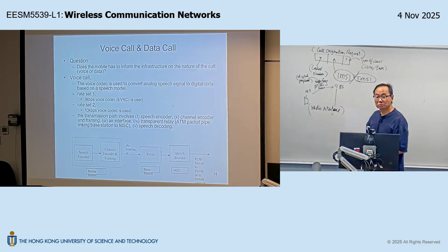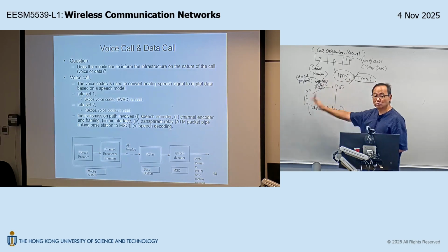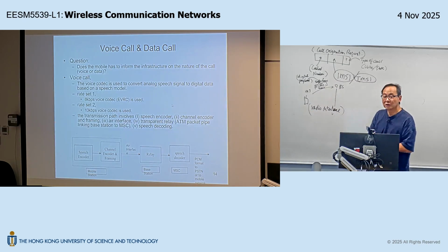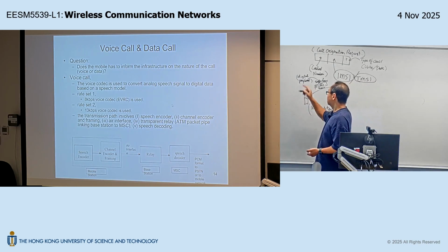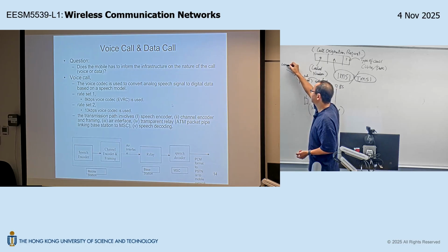And that's what the radio interface guarantees. You will be able to deliver 300 bits from mobile to the base station every 20 milliseconds, and vice versa. Now, this digital payload can come from two sources. It can come from the mobile station. It can come from compressed speech.